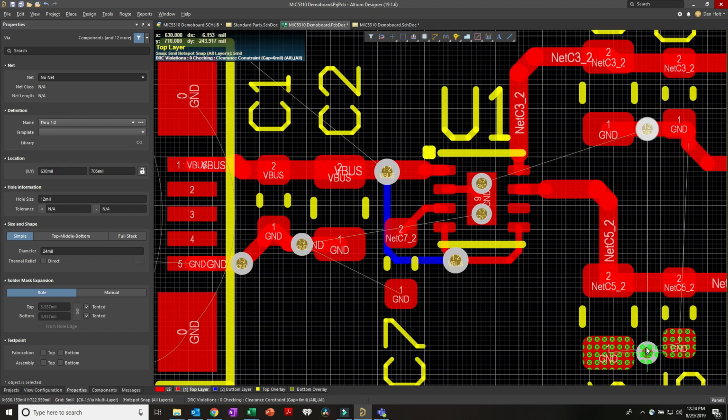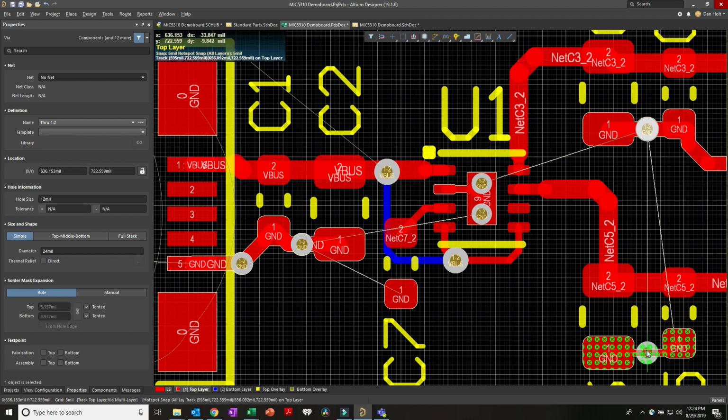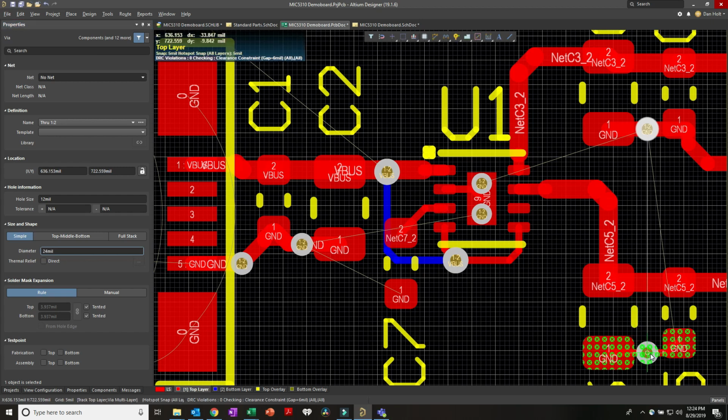Now if we go back to our schematic, we should see an extra pin there, which I'm just going to tie to ground. So now schematically we've updated it. Now let's just do a design update PCB. We're seeing that we're adding U1 pin 9 to ground. We're going to execute the change. And it's done. And now look, we have ground tied to that pad, and when I hover over it, you can see how it's highlighting the net.